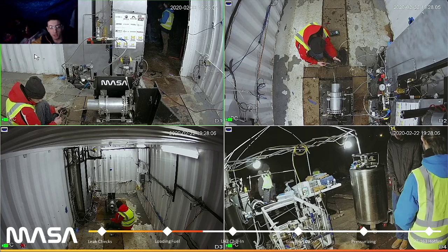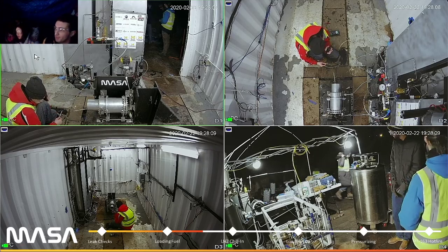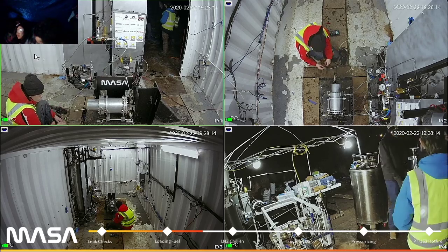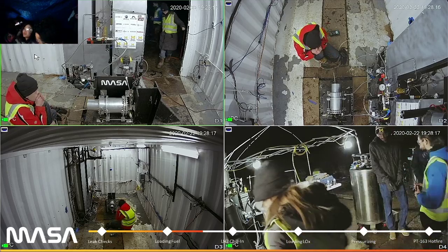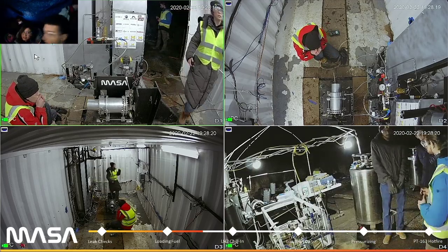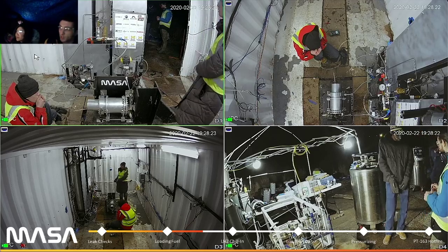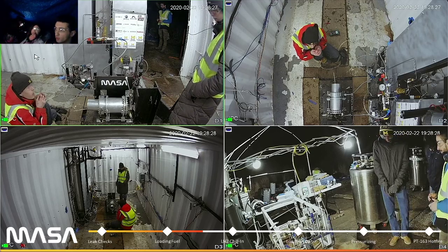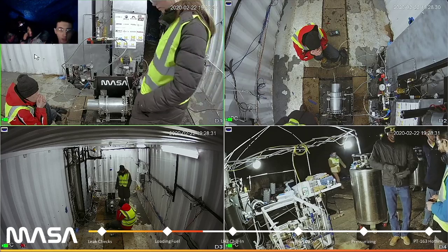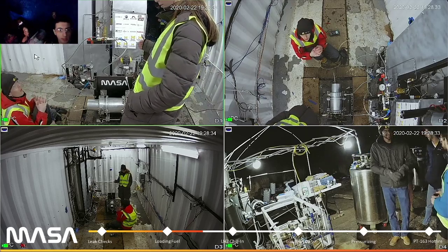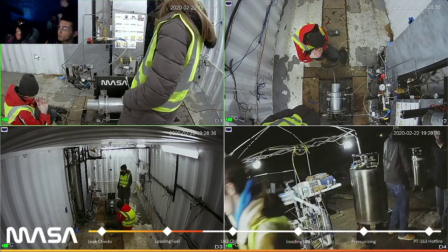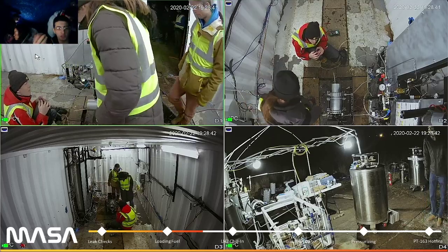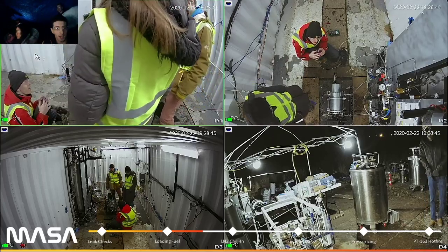For those of us who are just joining now, what are we doing right now? Are we going to be filling in the LN2? Chilling. So we chill in the line and then fill in the box. Right now we are doing our LN2 chill-in before we fill in the liquid oxygen. We're also doing some checkouts on the igniter system, making sure all of our auto sequence is working properly. You can see that up on the stream. If anyone has any questions, just send a question into the chat and we would be happy to answer it.